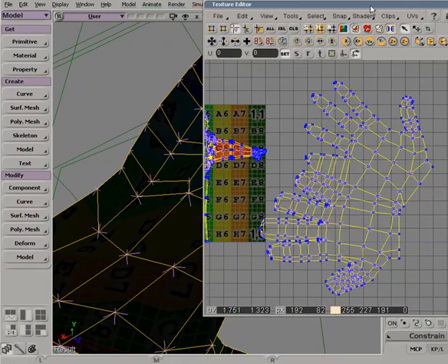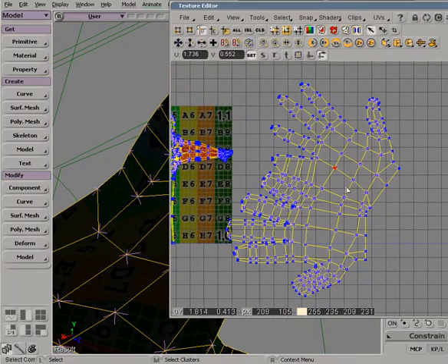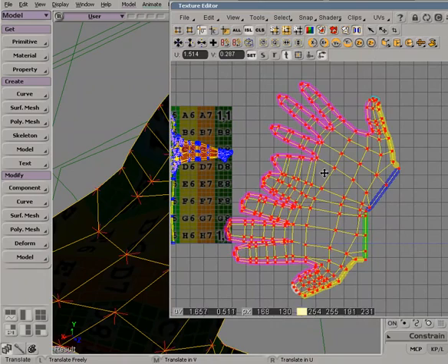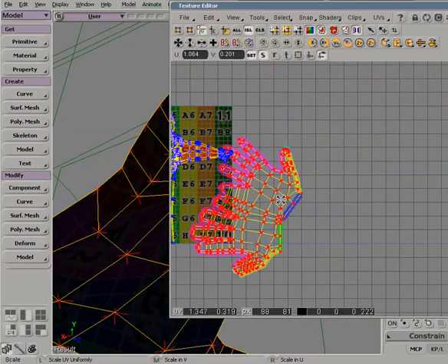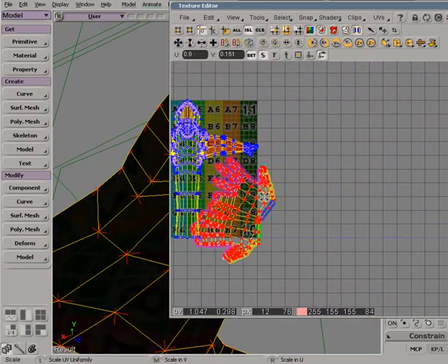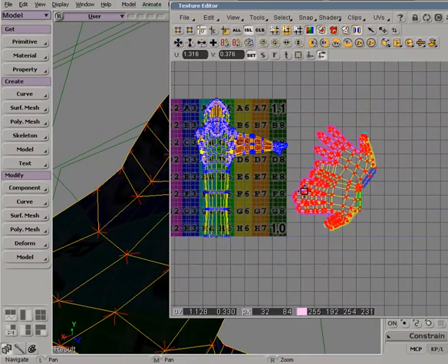Now we have a couple of UVs that have been moved together and now sewn back into one continuous UV island. So if I turn on my island selection and grab this, you can now see it grabs that entire island. And now with this new island, I can go ahead and completely scale these in and out. I can move this around or do pretty much anything I need.